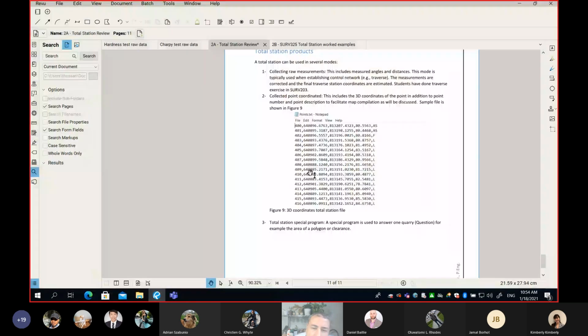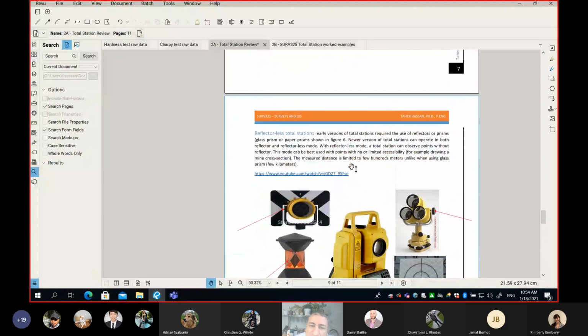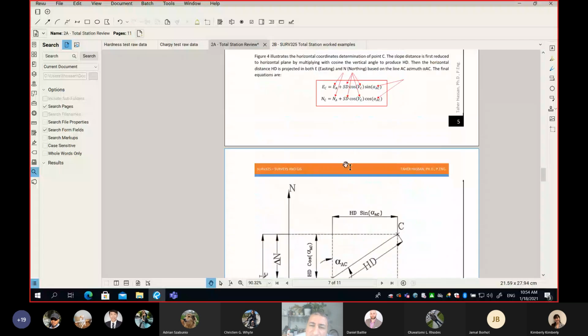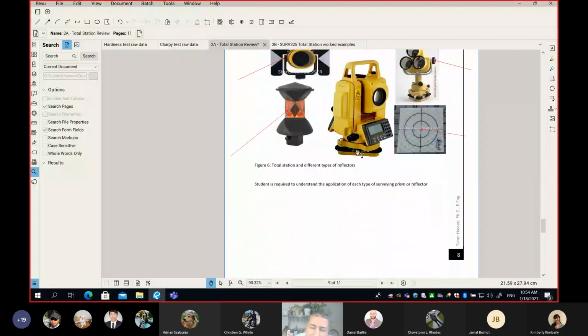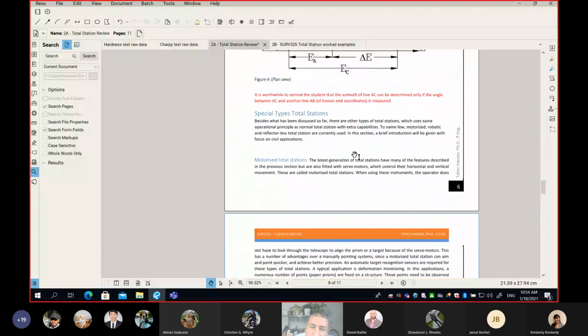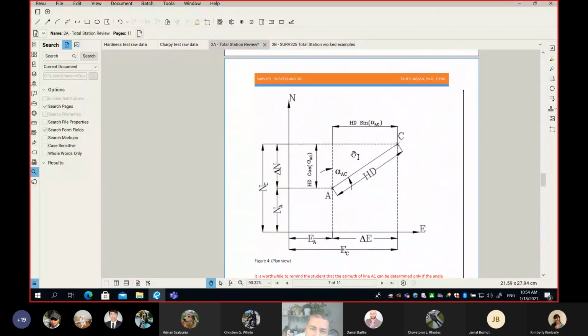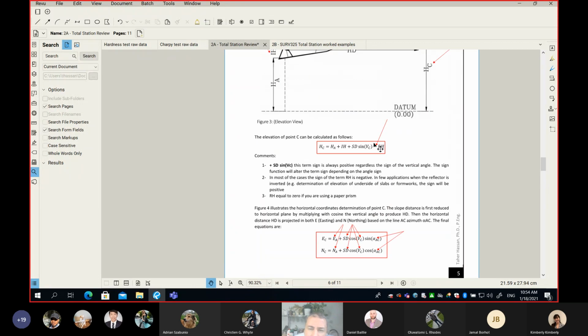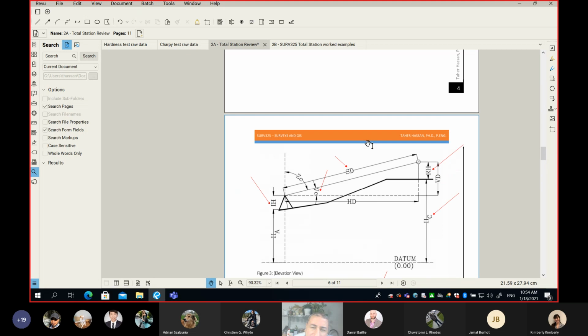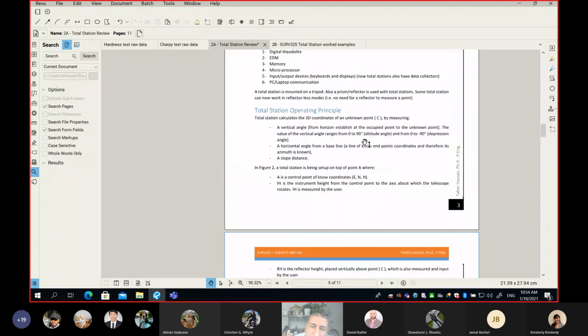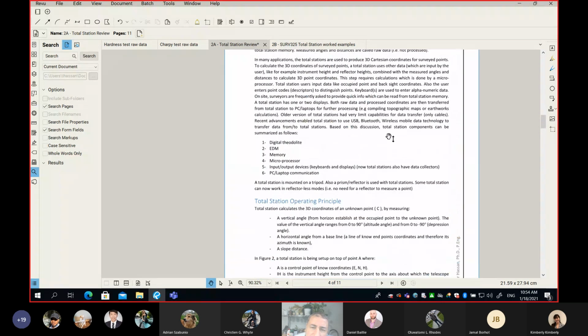For sure, you need to measure the point on the ground so you can find the delta in elevation. Our helper should do their best to align themselves under the point of interest. I know this process will have some error, but if you're careful, the error will be acceptable. Did I answer your question?